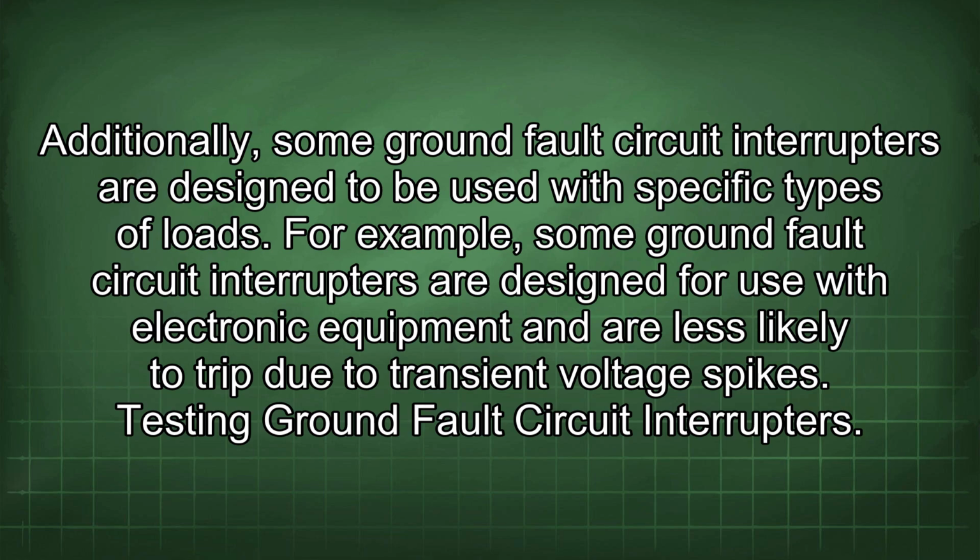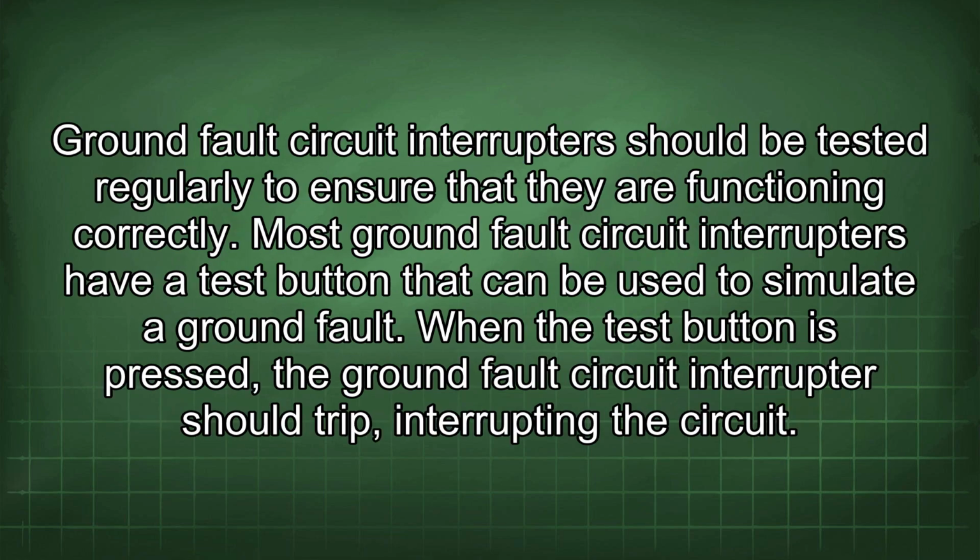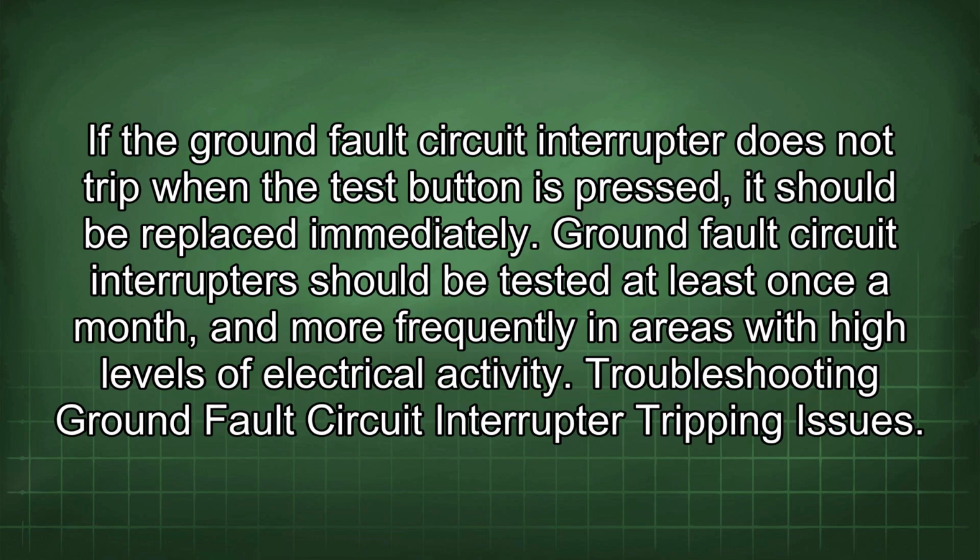Testing ground fault circuit interrupters. Ground fault circuit interrupters should be tested regularly to ensure that they are functioning correctly. Most have a test button that can be used to simulate a ground fault. When the test button is pressed, the ground fault circuit interrupter should trip, interrupting the circuit. If it does not trip when the test button is pressed, it should be replaced immediately.